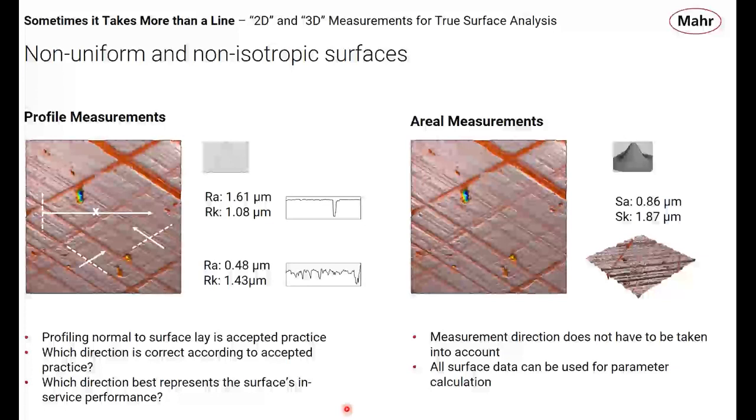If we measure from southwest to northeast, so down here, when we do this measurement and we cross one of those honed marks, we get a fairly large Ra value. We're going to get a pretty big Ra value. In the case of this measurement, where we intentionally tried to get down inside a hone mark, it looks rougher, but that's because the scale is different.